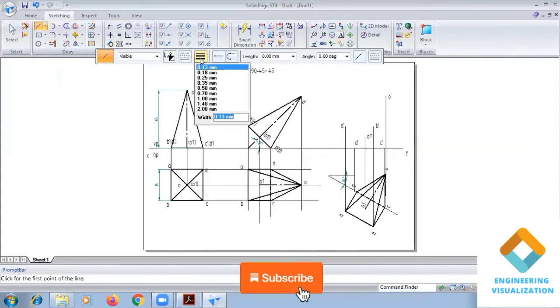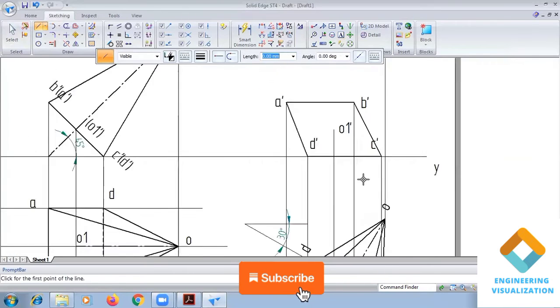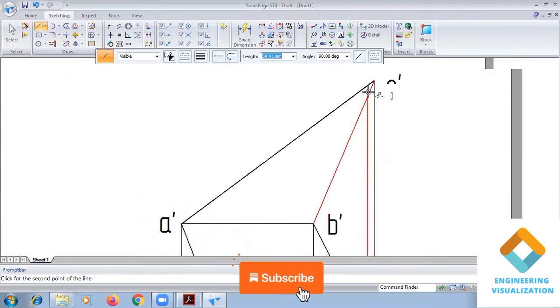So first we write the base of this pyramid. Okay. Next we draw the slant edges. If the slant edges pass inside of the base, that will be a dashed line. So you can see that from A dash, B dash and C dash it is passing outside, so no dashed line.